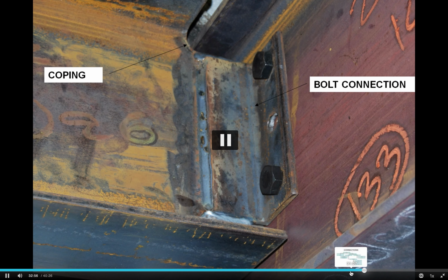All right, so this is another way of connecting the beams. You saw the column connections, and this is how you make a connection of two beams up in the air. We have what's called a connection piece, marked out, that angle piece that you see there. It looks like an L with a 90-degree angle, and you can see that one side was welded. So this connection piece was put on the beam on the left in the shop, so that when it gets to the field, you can use the bolts to connect it to the other beam.